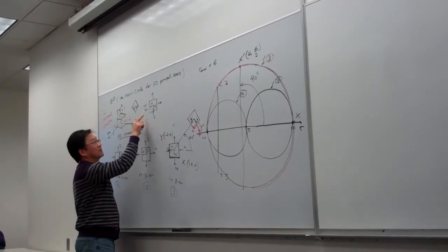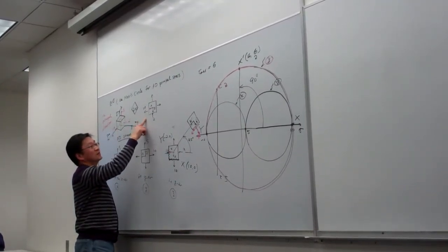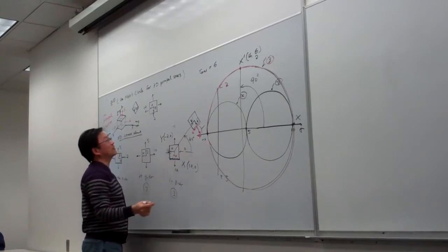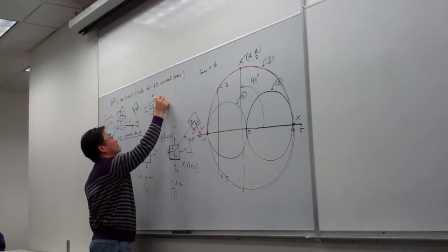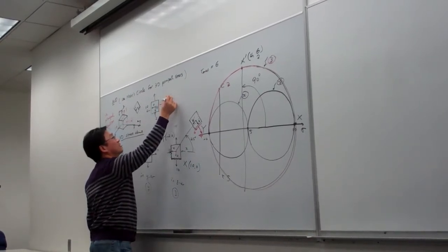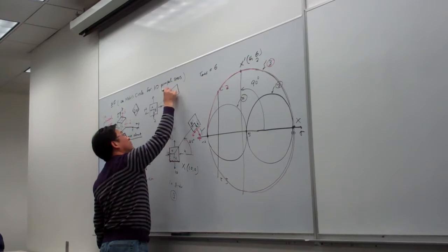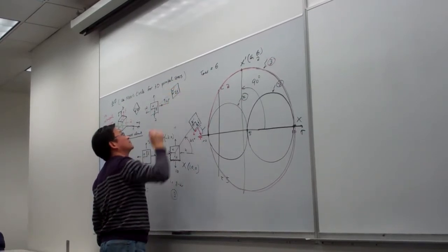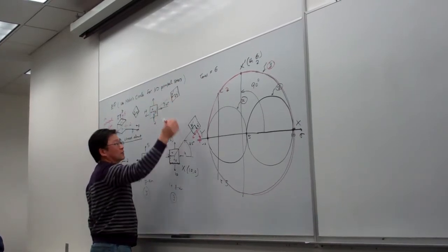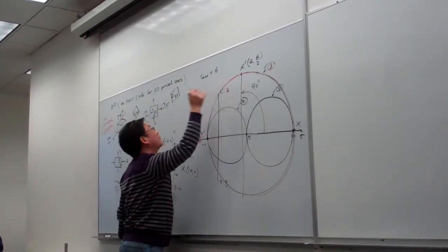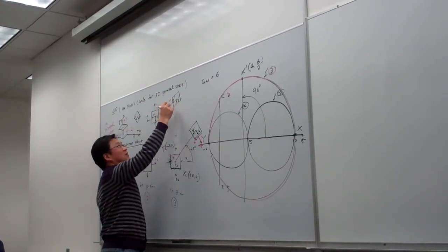So again, I try to fix the directions. This circle still corresponds to this one. Now we rotate 45 degrees, so that will be x prime and y prime like this. Let me fix this one. In x prime we have 4, so the normal stress is 4, and 6 is the same.